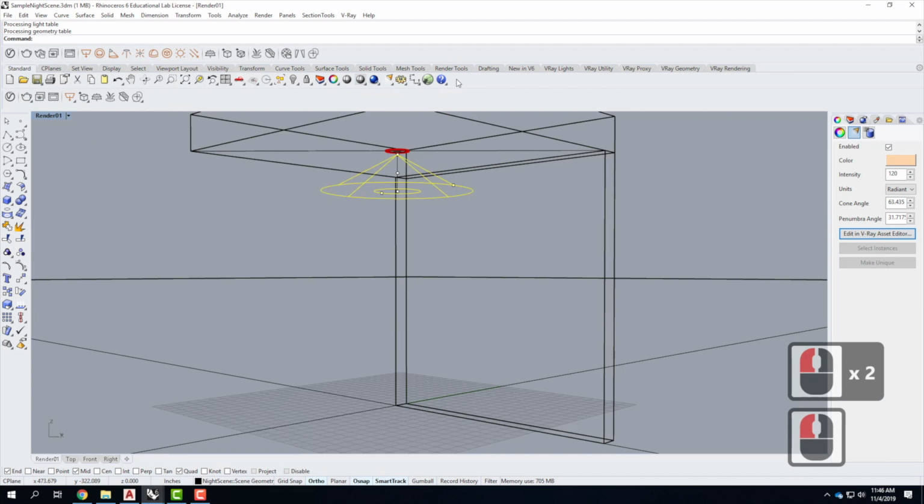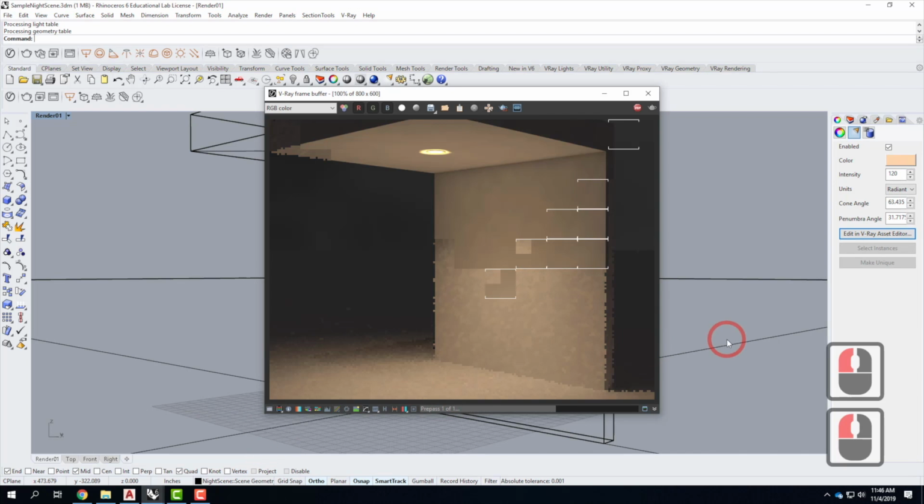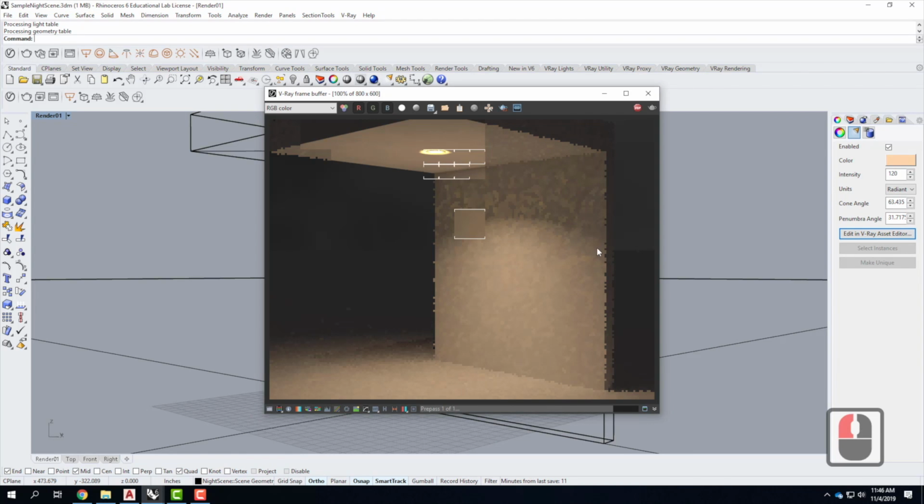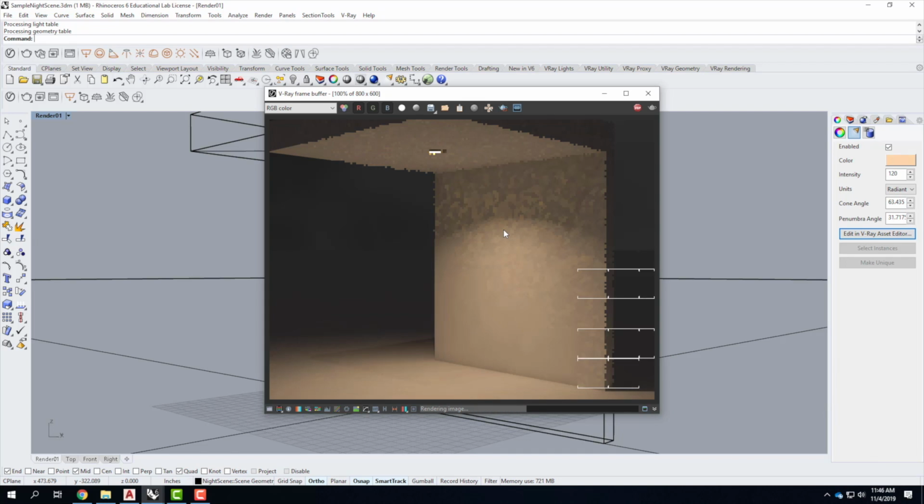It's the opposite effect. So I'm going to end up with very little light or arc on the wall. That arc is going to be much, much higher than it was in the original one. And so now it's a very kind of diffuse broad light. So I've changed what the lighting conditions are based on the geometry of the V-Ray light. Does that kind of make sense? So most of the time, the 1-to-1 rule is a pretty safe bet. You stick with that and you're going to generally be okay.